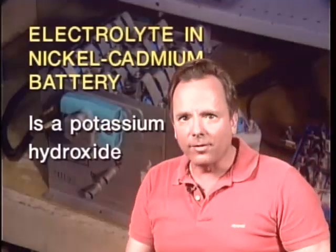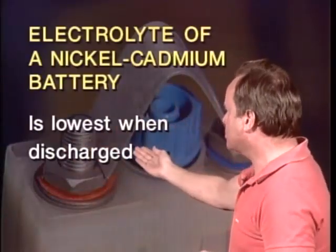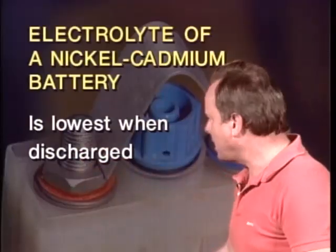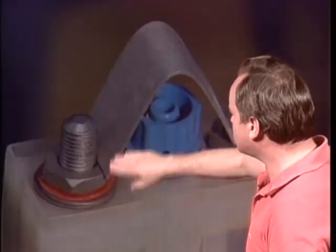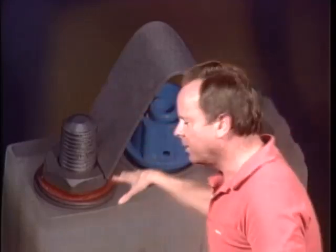Now, the level of electrolyte in a NiCad battery is low sometimes. Let's take a look at when the level is low in a NiCad battery, and the answer is when it's discharged. The level is lowest in a NiCad battery when it's discharged. By the way, you might be interested in what we're looking at here behind us. This is a NiCad cell, one cell out of a battery that is being strapped off to short it out to make sure that it's completely discharged before it's charged.